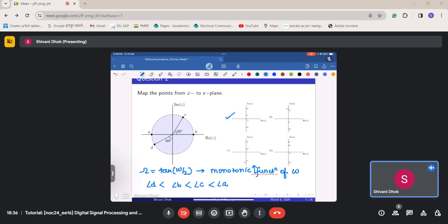Okay, I'll suggest you to check if the magnitude thing is 1 or not. Magnitude of z should come out to be 1. It must be 1 when you're setting S as j omega. Something there will be a mismatch. You can try doing it. Just check out all the things that we require in this particular transform, in bilinear transform.